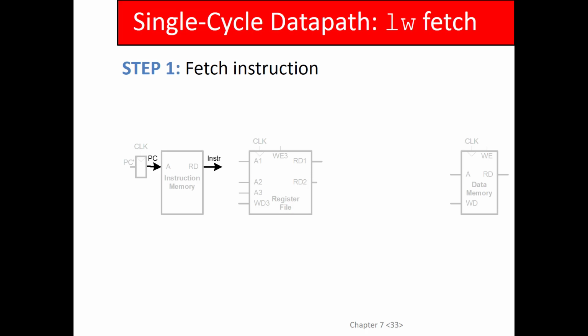So the way you've got these connected is the program counter is pretty much wired directly to the instruction memory. That's pretty easy. Just draw a wire. Well, again, it's not one wire, it's actually 32 parallel wires, but when you draw block diagrams like this, multi-bit signals are drawn as one wire. Something you've got to get used to.